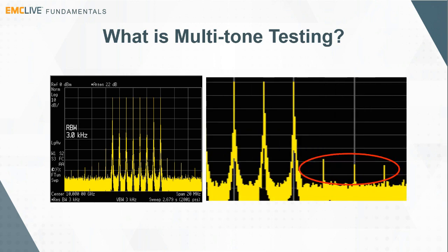When more than one tone is injected into an amplifier, intermodulation products will be exhibited as shown here. EMCware controls the maximum allowable intermod products and harmonics, thus assuring these nonlinear signals do not impact the desired test level. The ability to measure each discrete frequency component requires a frequency-selective receiver.